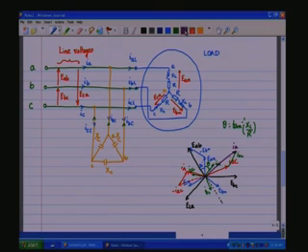So, this would be IA under the condition that we are using this capacitive reactance to pump back the reactive power. So, we invert the direction of the currents there, and the resultant IA here is now leading the voltages rather than lagging the voltages, which would have been the case if it had been just the RL load.